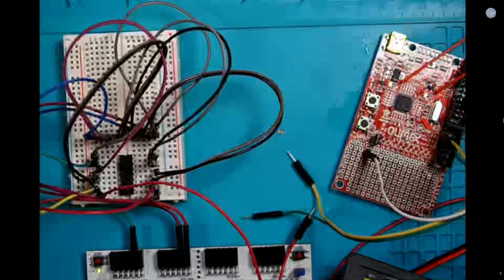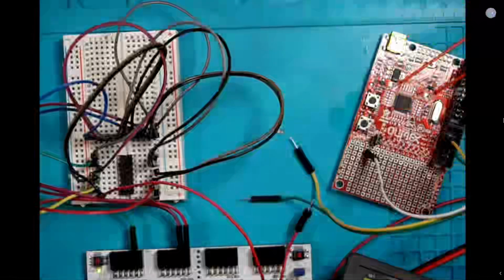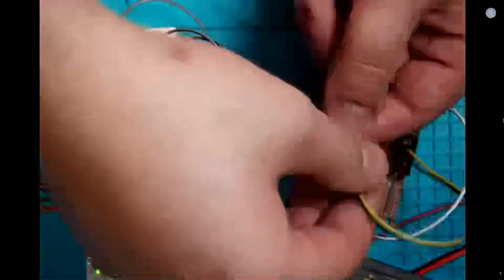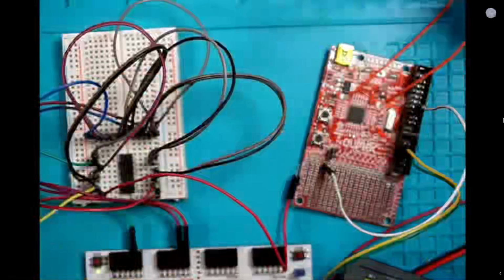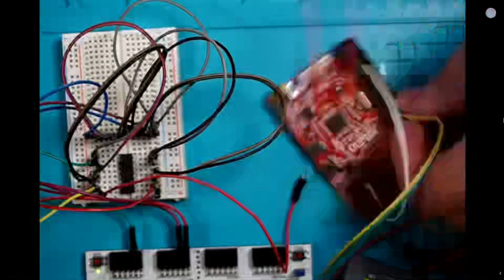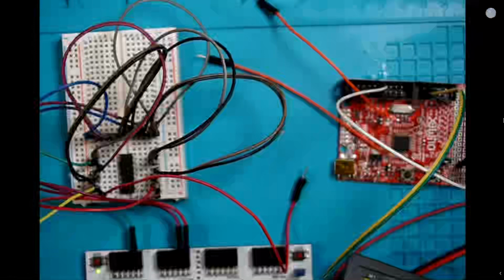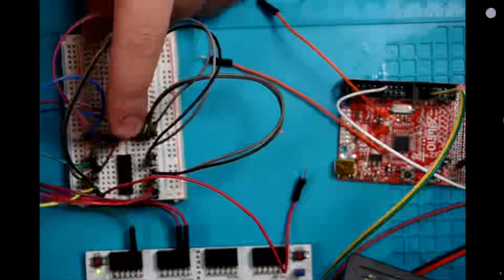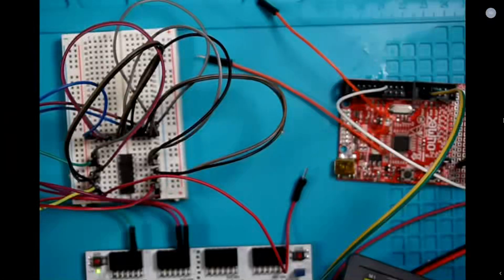Whenever you have an analog device, you want to make sure that you don't use any of the inputs that are not part of the circuit, essentially. So everything that I'm not using, I'm getting rid of. I still need to connect the TX and RX of the board. I'm going to connect them right there. That's where the TX and RX are exposed. These orange wires I'll want to connect to the actual output of this multiplexer. Wherever we have this yellow wire is where the output is going to be, according to the schematic in the data sheet for this multiplexer.